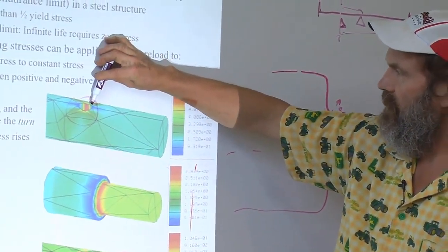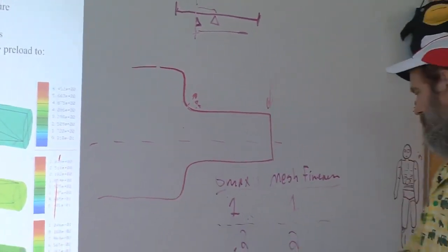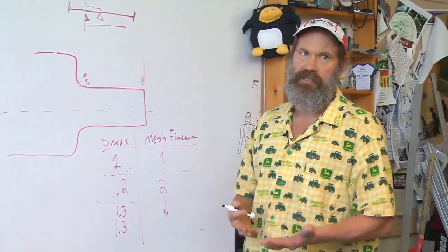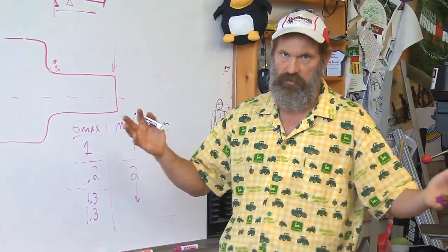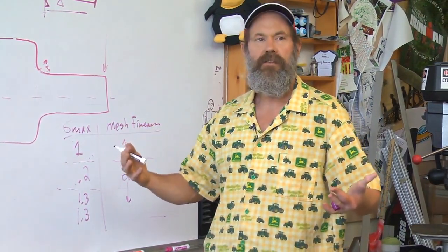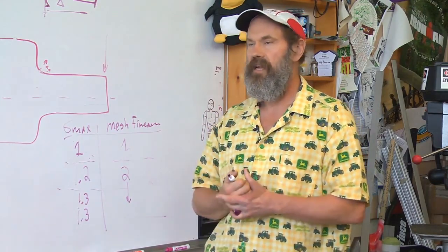And you say, well, if I'm doing this fine meshing and I've got that hole, why do I bother to do this? Why not just start with a very fine mesh? Because it takes a lot more computation time, even in today's world of super fast, wonderful, marvelous computers. As you get the structure to be more and more complex, it can really start to drag down the analysis, particularly when you start wanting to play what-if analysis.